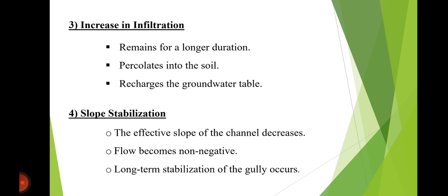So, the effect of a series of check dams: in long or steep gullies, several check dams may be constructed at suitable intervals. Each structure reduces the energy of the water, creating a step-like sequence that controls the erosion throughout the gullies.